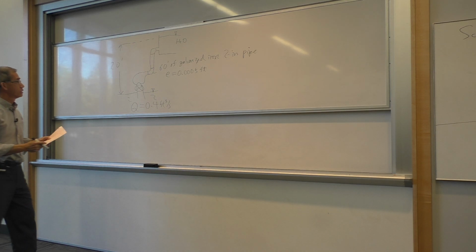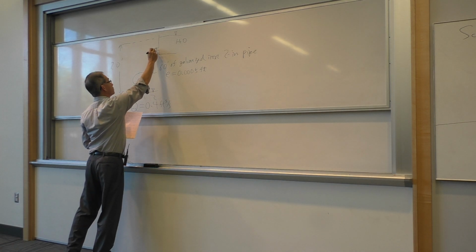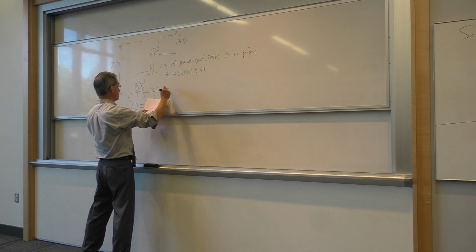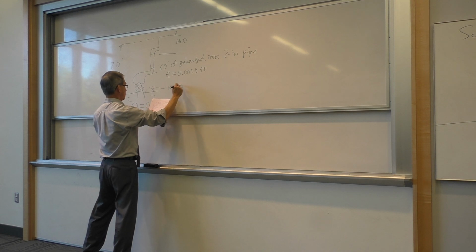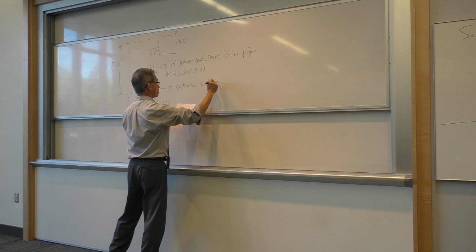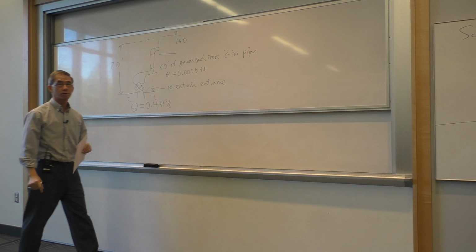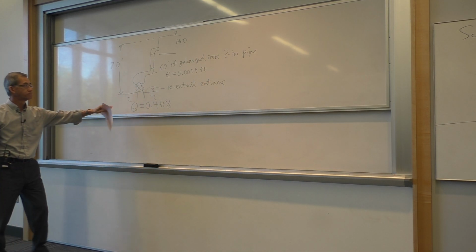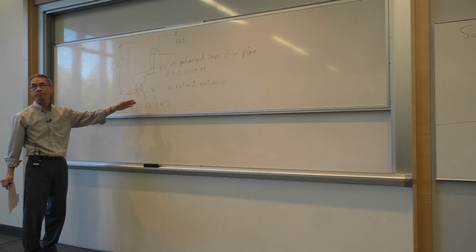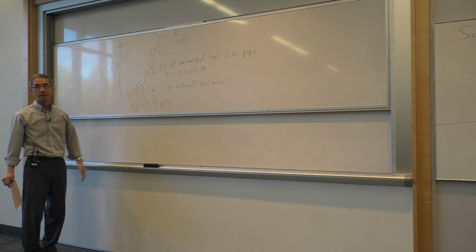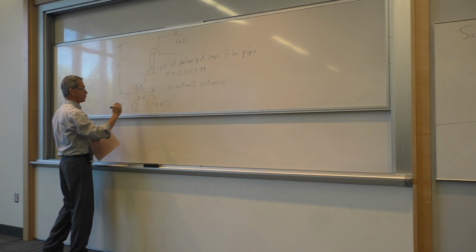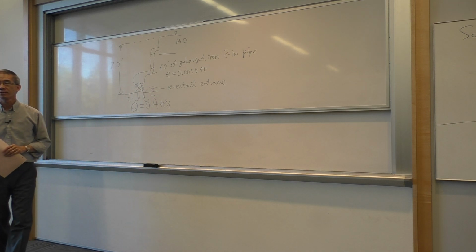And the way the water is being pulled into the pump and the flow system is via a rather peculiar name. It's called a re-entrant entrance, meaning that there's no attempt to smooth the flow that gets pulled into the pump. It's a sharp intake, and the water is not very efficiently being sucked into the flow system.